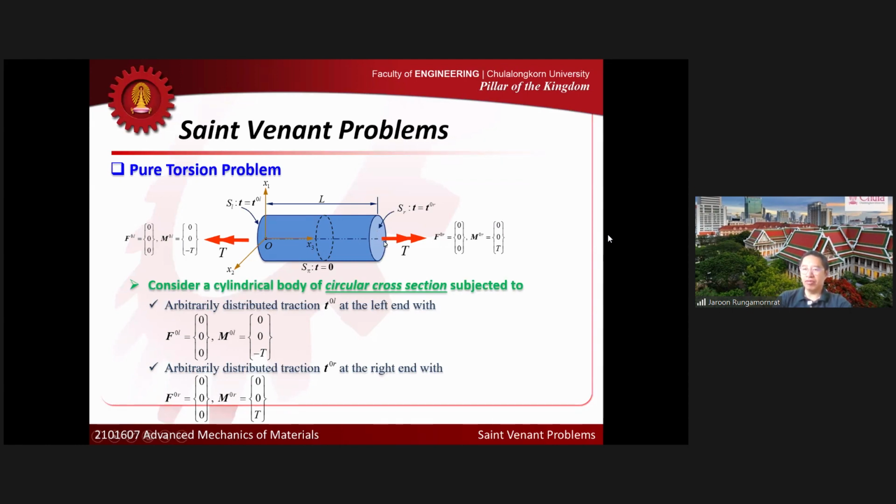If you remember, the shear stress is simply T multiplied by R divided by J. That is the formula that we call the torsion formula. That should be well known to you. If you want to compute stress at any location, you just use that formula. That is what we got in that basic class in strength of materials.